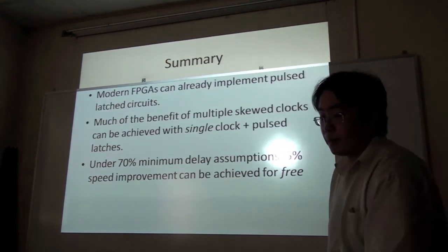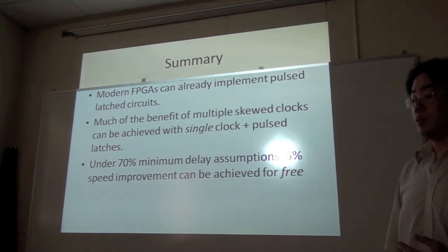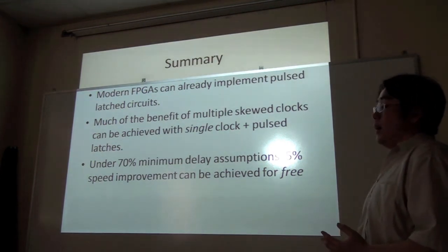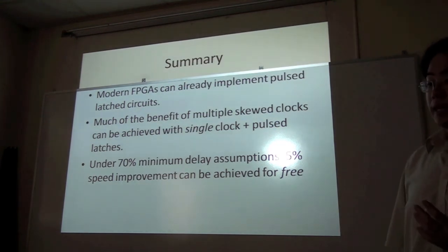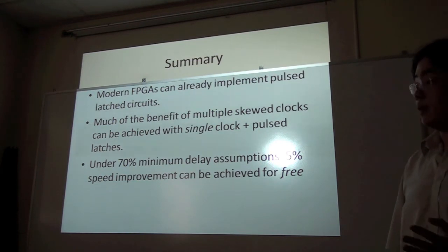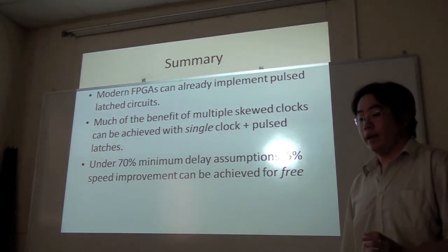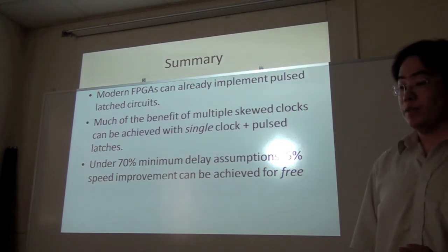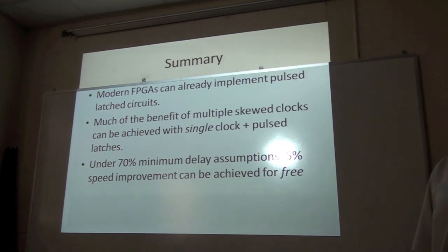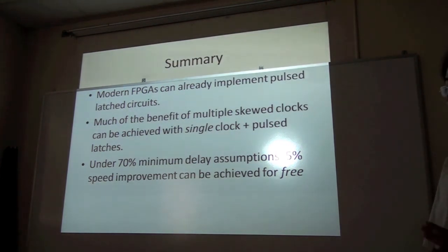So in summary, modern FPGAs already provide us the capabilities to implement pulse latches. I showed in the results that much of the benefit of using many skewed clocks can be achieved by using a single clock with pulse latches. Under 70% minimum delay assumptions, we can achieve a 5% improvement in speed, essentially free of power or area overhead.